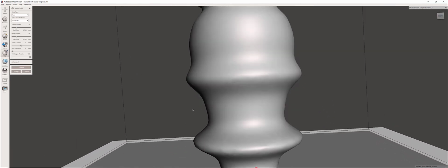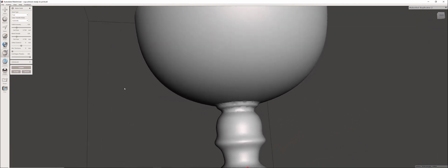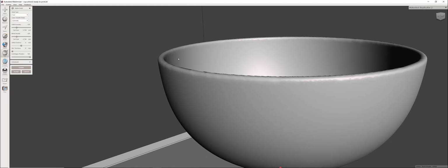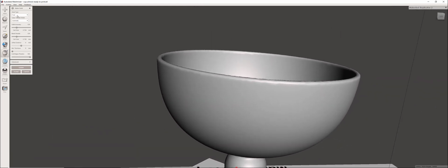You see that row over there. See, so it doesn't have too much quality. So the quality, the accuracy of our shape, we give it with these options over here. So first we're going to change from fast to accurate, or you can also use sharp edge if you have some sharp edge, but I deleted all the sharp edges from our cup model. Remember those sharp edges that we made with the tangent with the circle. Okay, that's a sharp edge. So we're just going to use accurate. Okay, click it, what happened?